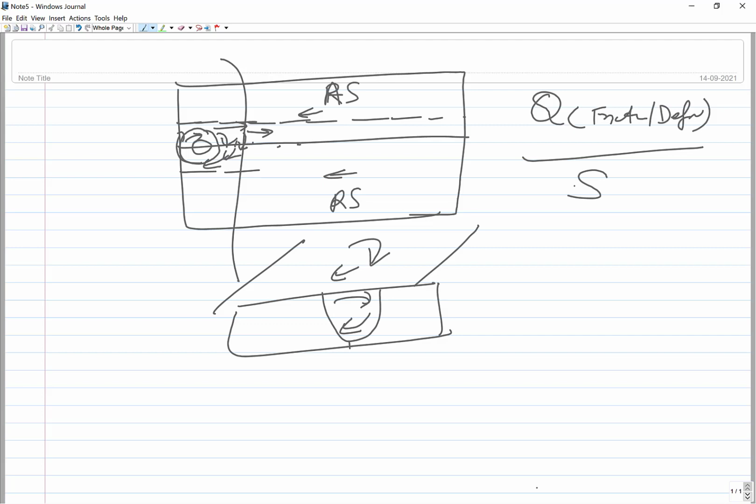So there is a welding speed, and there is a particular kilojoule, that is the heat which is being generated in unit time, and the welding speed which is being given. So we can easily find the heat being delivered to a particular location for a given welding speed. So the net heat input in kilojoule per mm can be identified from the frictional and deformational heat and the traverse speed, or the speed at which the workpiece is moved with respect to the tool.